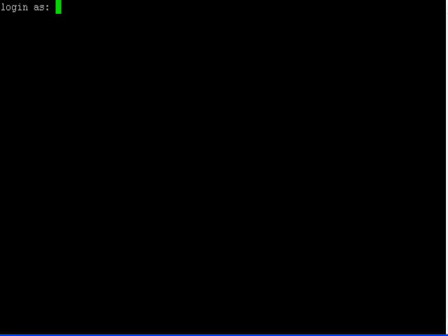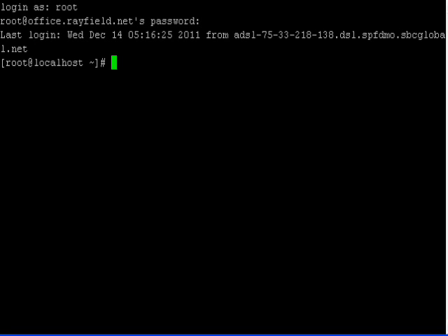Once the cBridge controller is finished booting and you're ready to start configuring it, you'll have a login prompt. It says login as. At this point, we want to type in the word root and press enter on the keyboard. You'll now enter the default password. You'll notice as you enter the password, you do not see it printed on the screen. This is for security reasons. Press enter. We should now end up with another prompt ending with a hash or pound symbol.